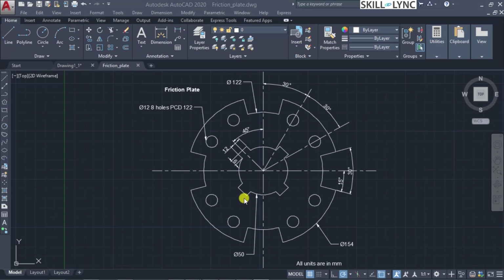So how it will be useful is that you can manipulate the specific layer that you want while you hide the others. For example, after constructing this drawing and you are passing it down to the next stage of processing, suppose they have to work only on the annotation elements and not on the drawing here, then they can hide this drawing entirely and look only at the annotation. Suppose one of the designers has to modify the title block or put in a revision, then he can focus only on that and hide the rest so that he does not misplace or misenter some information.